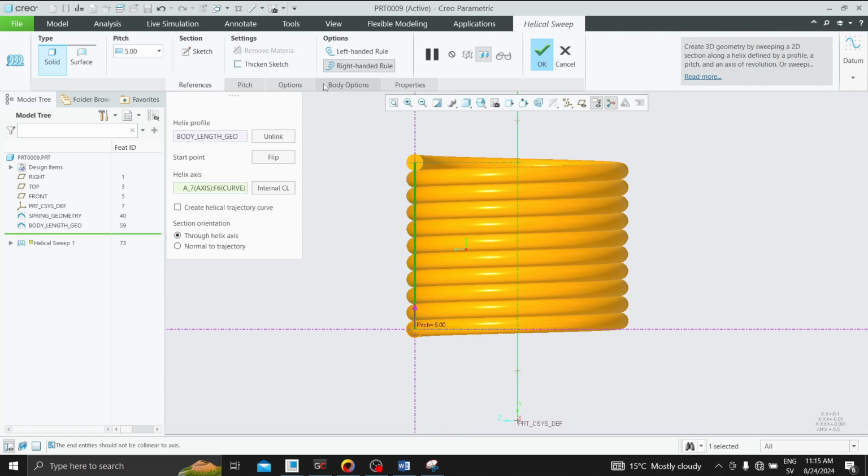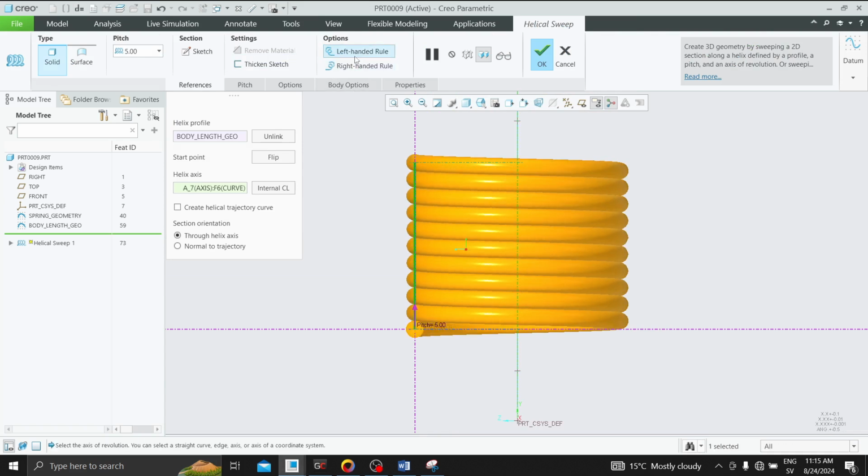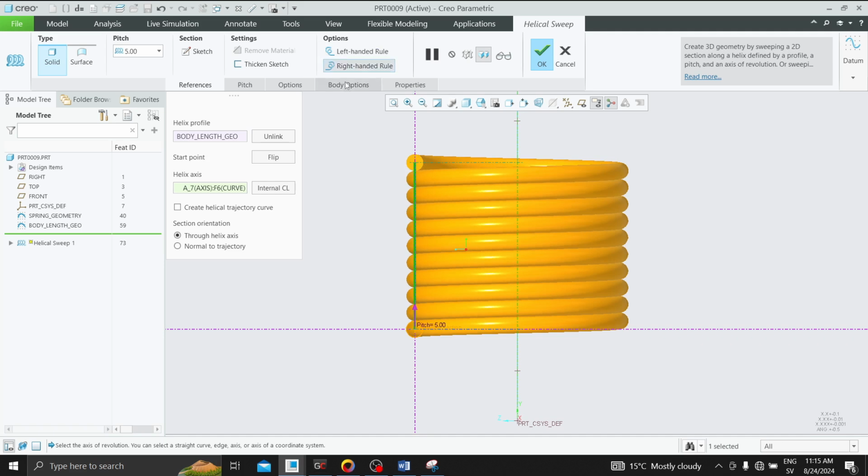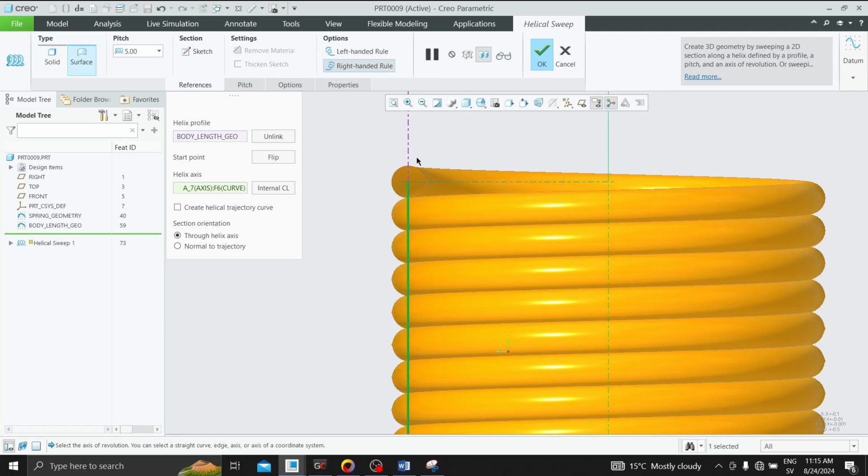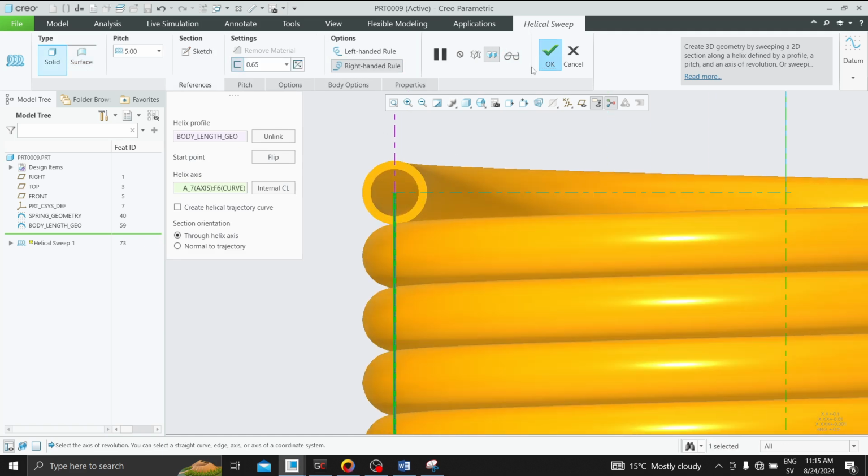And there are some parameters here that are very important on what you are going to do next. You can go clockwise or counterclockwise, and you can use a surface like that or body. If you want a surface, you can as well do a body thicken, hollow.